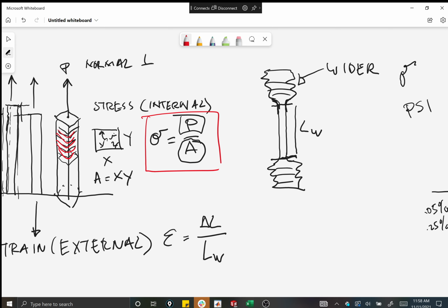Because like he was saying, you'd pull it up and keep getting thinner and thinner, and since every single cross-section is taking the same load, at one moment it's just going to go pop, and you're not going to see it anymore. And like, oh yeah, that's great, tension. That's not what happens, and you can go look at a pile of these that have been broken, and they're broken in all different places, because there's some kind of imperfection. That's at least the way I understand it.